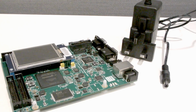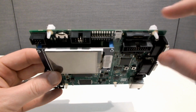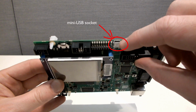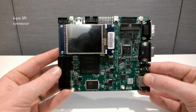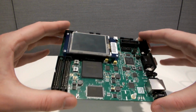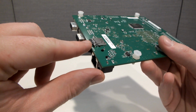The board comes with a 12-volt power adapter for plugging into mains or line power, and there are a number of input and output sockets for connecting to a range of peripherals, including this mini USB socket. At the top left of the board is a 6-pin SPI connector. If you want to use the Mbed OS file system, you will need to connect the SPI to SD card adapter here.